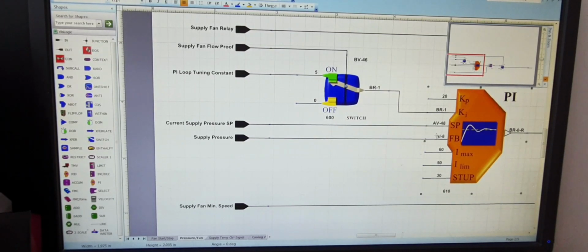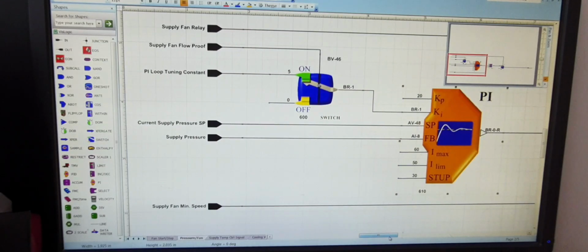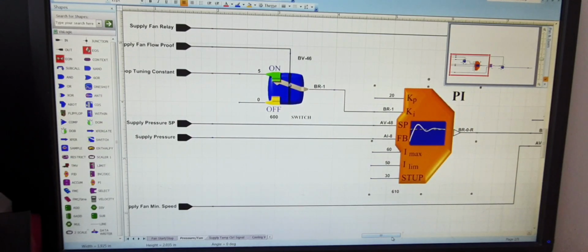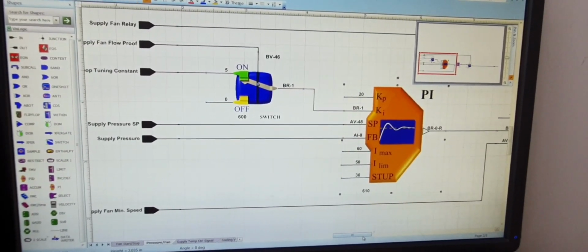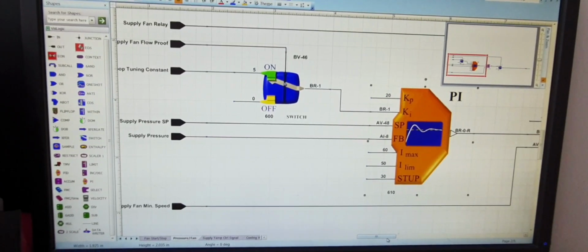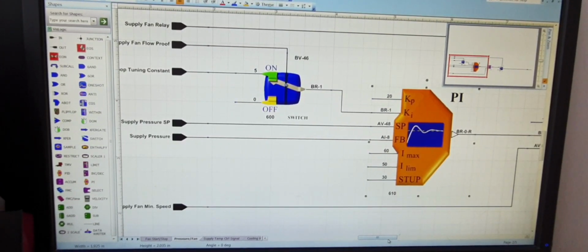What we want to do is maintain the set point. The primary goal of this program is to maintain the fan speed at a specified set point, so that it meets the exact design requirements of the duct and its entire length and the VAVs it's controlling. We want to make sure that none of the ducts are compromised, and you have the correct amount of airflow, the maximum CFM that the AHU is generating. We want to make sure we're not over or under calculating and designing, so that some areas will have high airflow and some areas low airflow.